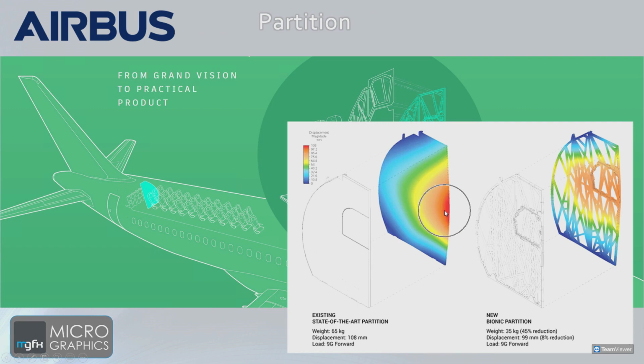So if you take a look here, this is something I just want to point out. You'll notice that when the force was applied and a simulation was run, you can see they've got this really cherry red hotspot, and it then very quickly fades through the different magnitudes all the way up until you get the light blue, which is barely touching the edge, and then these outer edges aren't really under load. So it does spread out evenly over the area, but it's very concentrated over here.